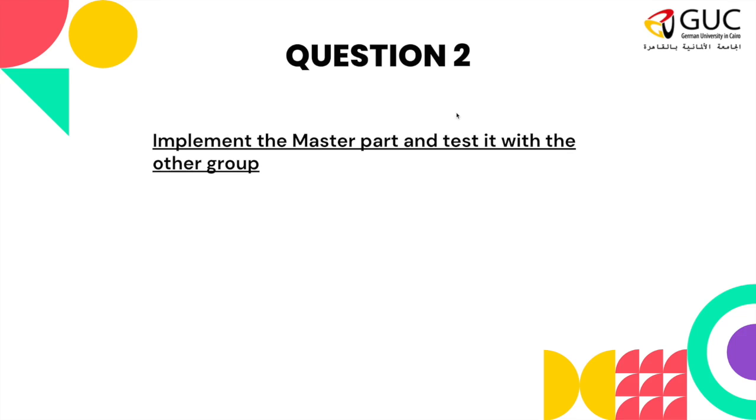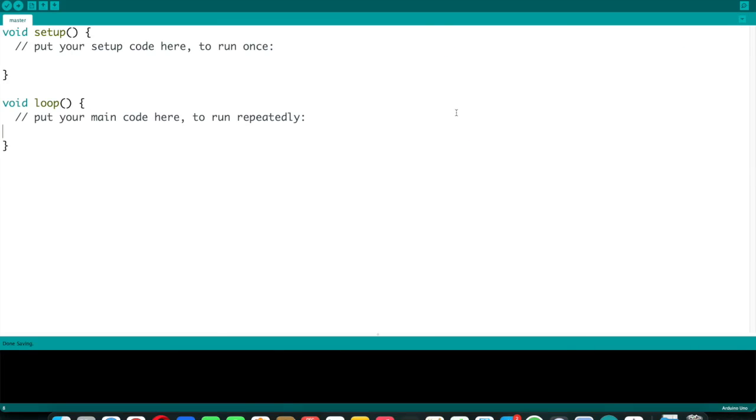So if we open our Arduino IDE, which has the setup and loop functions, and as you remember, the setup function is only executed once at the beginning of the code. However, the loop function is our main function, which will execute forever. So you put initializations in the setup function, and then the main logic inside the loop function. And this is written in Arduino C.